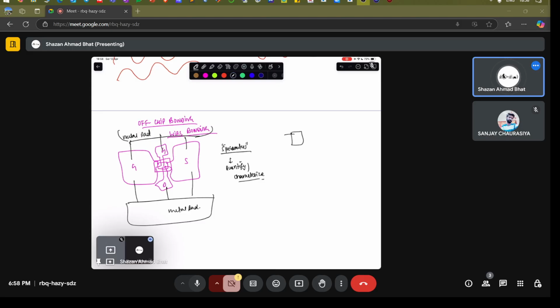These are thin metal wires which are bonded to the chip in order to take the output or characterize it. They are bonded by, for example, temperature. There can be pressure applied on it in order to bond it. There can be ultrasonic waves used in order to bond it. But note that these are going to add extra resistance in the system.